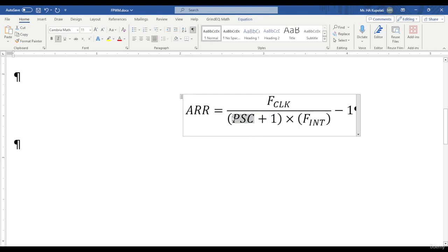You select the prescaler, which in this case is going to be 1. You select that prescaler, keep in mind the frequency of your clock, and then you have all the values and you can actually calculate the ARR. So off screen here, when I calculate this particular value, it's 8499. Also, again, just keep units constant. If you use kilohertz here, use kilohertz there as well. You don't want to be making mistakes here, because this matters a lot. It's relating to the time.